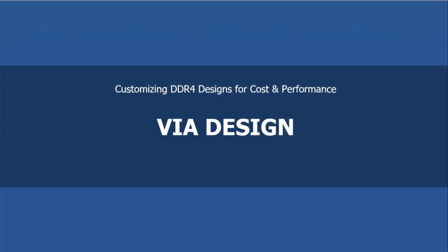Now let's talk about VIA design, which is everyone's favorite topic. With DDR4 data rates, the VIAs are not as critical as in SerDes applications in which the traces tend to run longer at higher data rates. But we want to take a look at different options so that you are not caught by surprise, as I'll show you some cases here.